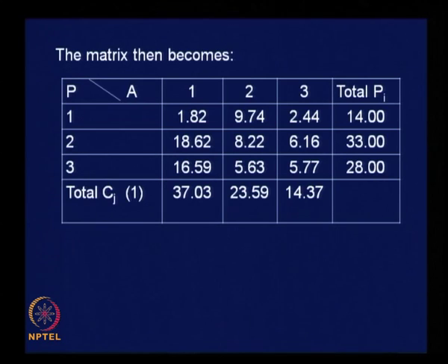The cell values of the matrix are nothing but the trip distribution between zonal pairs, and we found that the sum of the cell values along each row works out to the corresponding total trip productions of the zones, whereas when you sum up the cell values along columns, they are not giving values corresponding to the total trip attraction by the traffic zones. That is a problem.